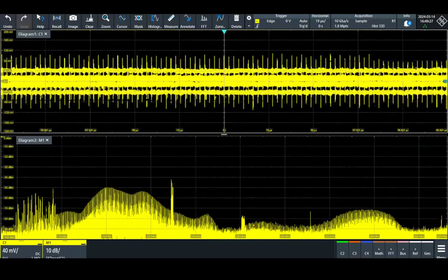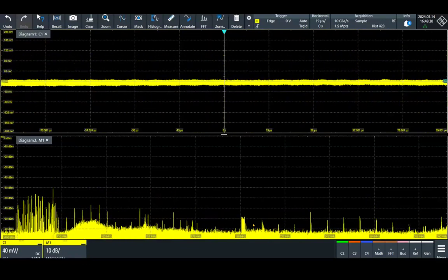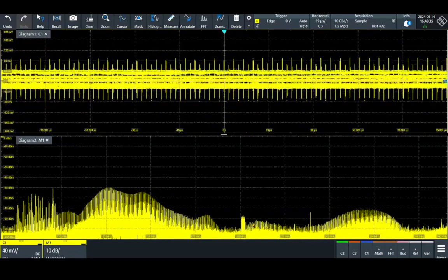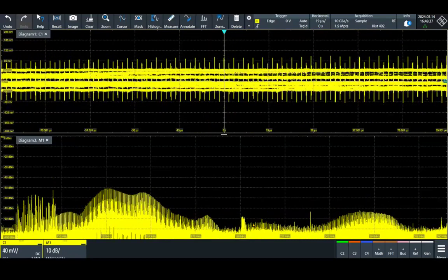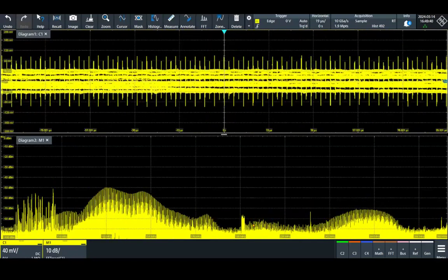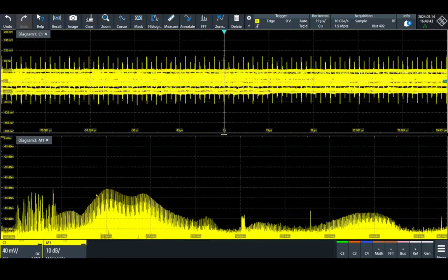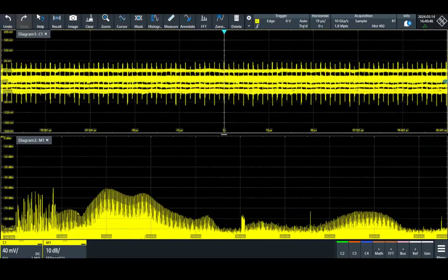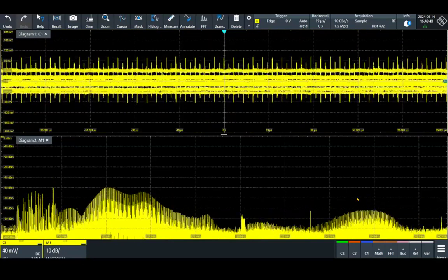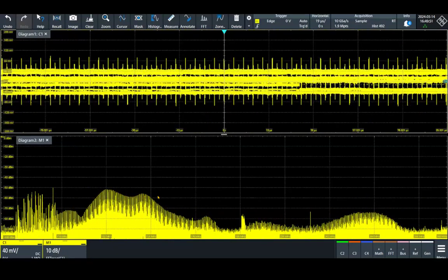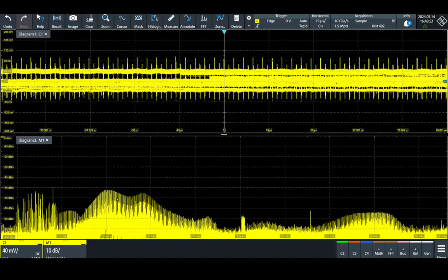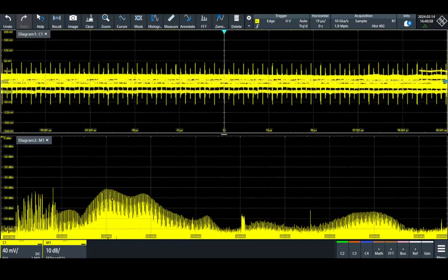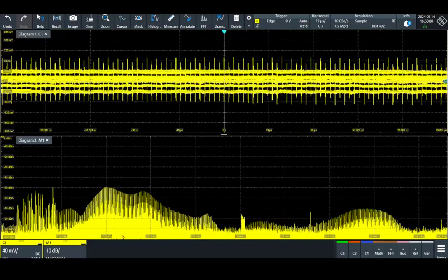Let me switch off. We switch off. Now I switch on. So clearly, what I am creating is this big mountain that is over the 108 megahertz of the FM band. This is the area where we are failing, okay? This mountain you see here is a broadband emission in this area, and obviously I have more emissions here, but consider, for example, that the frequency between 130 and 150 megahertz is the area where you are over the limits and you want to reduce these emissions.